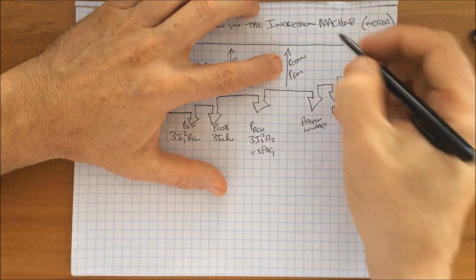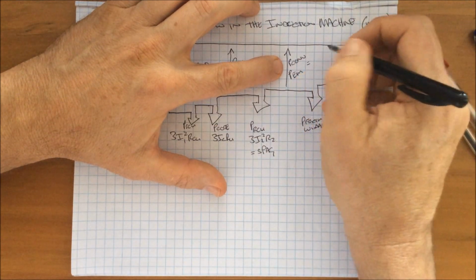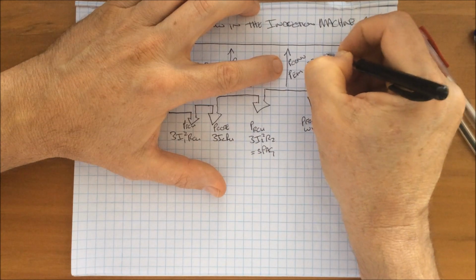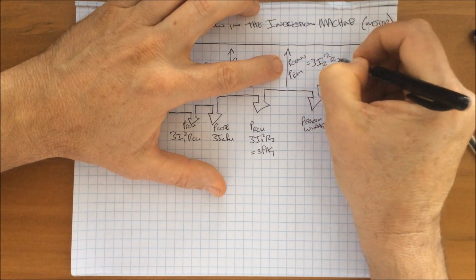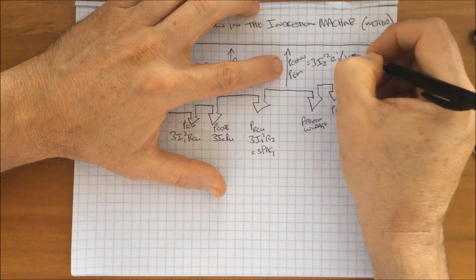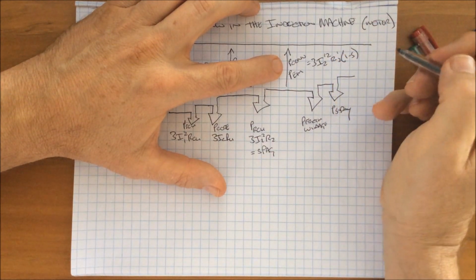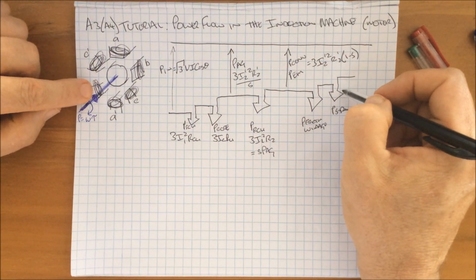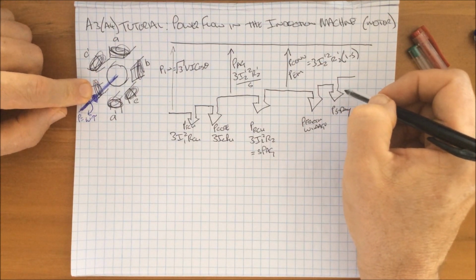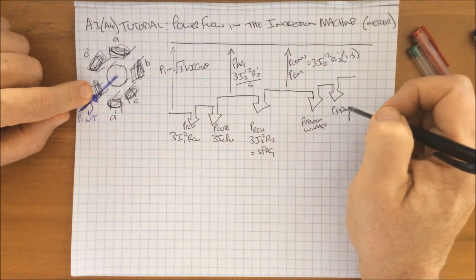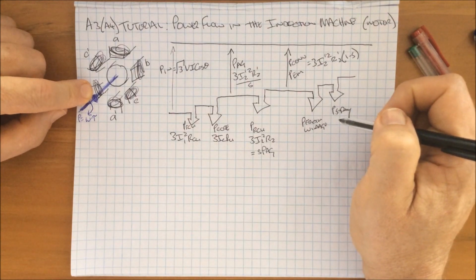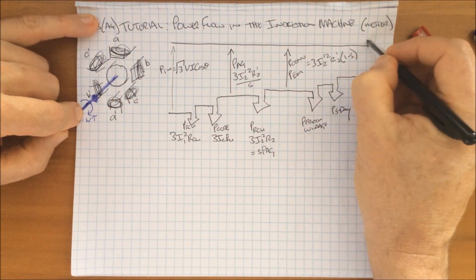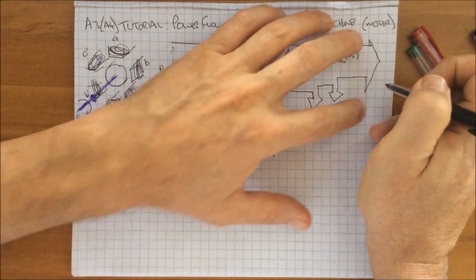As an aside, and back to the equivalent circuit, this power here can be found by 3 I2 squared R2 (1 minus the slip). Now, once we've taken care of the losses through the ball bearings here and the fan and whatever stray losses that might be floating around that someone's forgotten to include earlier, that is our output power. This is our mechanical power that we actually get out here.